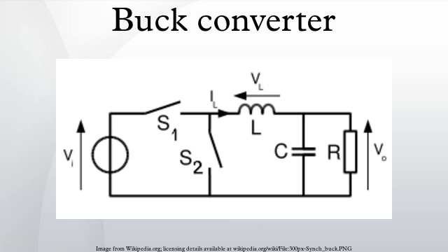Where RON is the ON resistance of each switch, and RDCR is the DC resistance of the inductor. The duty cycle equation is somewhat recursive. A rough analysis can be made by first calculating the values of VSWITCH and VSYNCHSW using the ideal duty cycle equation. Switch resistance, for components such as the power MOSFET, and forward voltage, for components such as the insulated gate bipolar transistor, can be determined by referring to data sheet specifications.